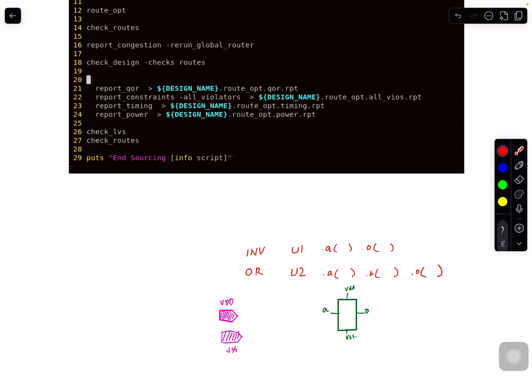You're telling the tool, I have created top level ports or terminals at the top level, and I will assign different metals to them, and logically connect this one to all the VDD pins of every cell, which are on the same voltage, of course. Similarly, VSS needs to be connected to all the VSS pins, and that logical connection is important.